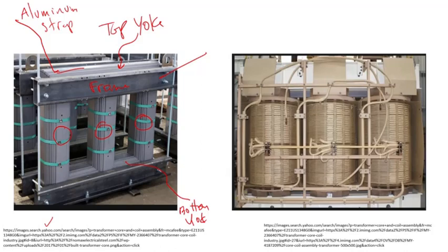But the frames have to be isolated or insulated from the tank, because the frames, or the core and coil, so basically this assembly here, you have the windings and the core held by the frames. It has to be dropped inside the tank, so they have to be insulated from the tank, because the tank is grounded.